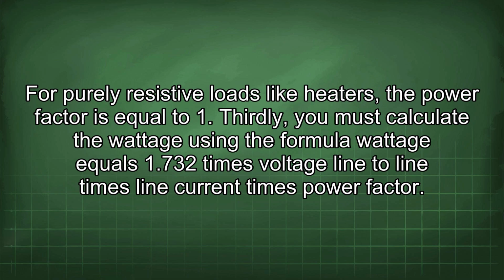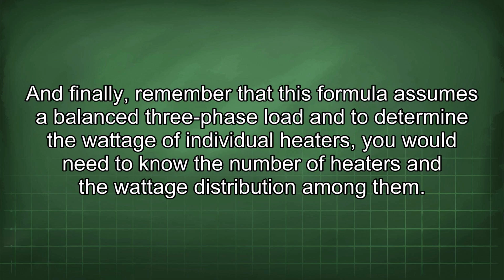Thirdly, you must calculate the wattage using the formula wattage equals 1.732 times voltage line to line times line current times power factor. And finally, remember that this formula assumes a balanced three-phase load, and to determine the wattage of individual heaters, you would need to know the number of heaters and the wattage distribution among them.